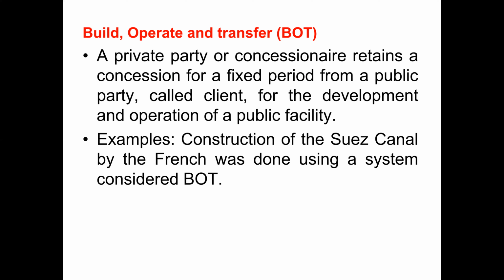So here they are going to give another method. I'm going to mention that we can adopt a build, operate, and transfer project delivery approach to finance projects. Okay, this is very good. These days it's a good approach. A private party or concessionaire retains a concession for a fixed period from a public party called the client for the development and operation of the public facility. Okay, so they give an example like the construction of the Suez Canal by the French, which was done using a BOT approach.